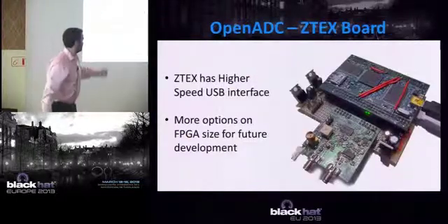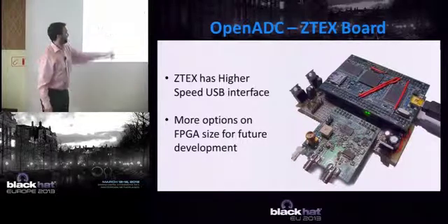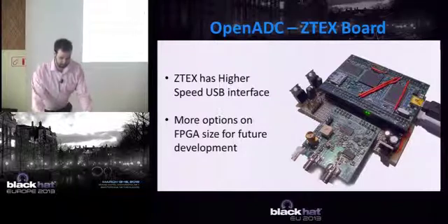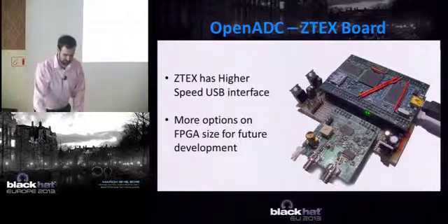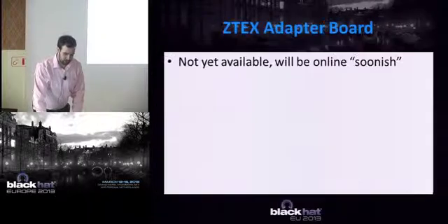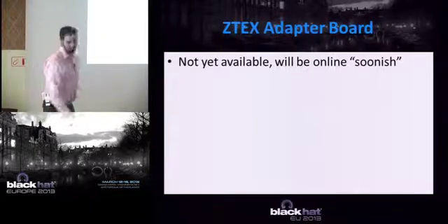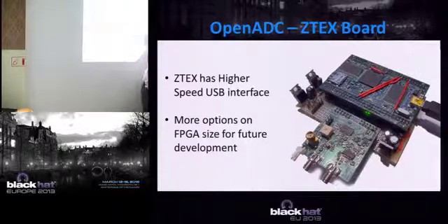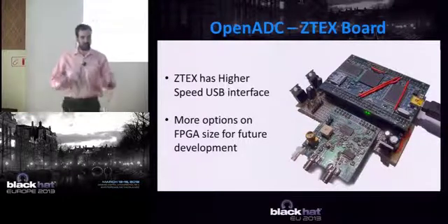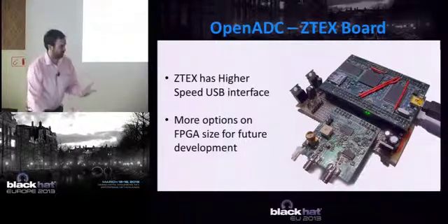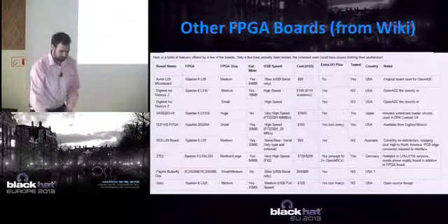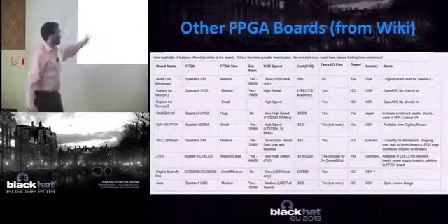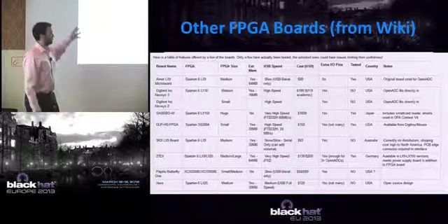Or there's a Ztex, a German firm that makes these other FPGA boards that have a slightly faster USB interface that I also use. And I have both of those versions here if you want to take a look at them. And I actually am trying to build an adapter board. Right now, you'll notice you have to do all this wiring yourself and add some voltage regulators. At some point, there'll be an open hardware adapter board if you don't want to have to do all that wiring, but it's not up yet. As I say, if you already have an FPGA, depending how proficient you are, you might be able to just use it and get it working.